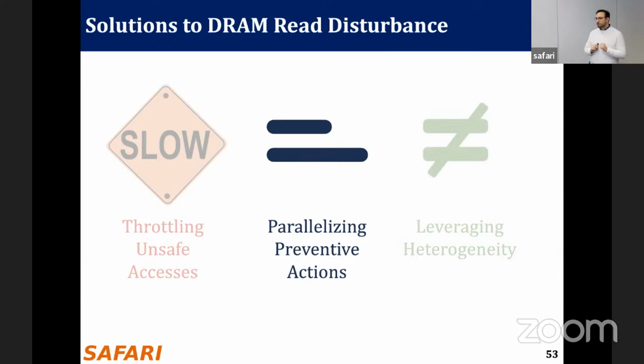But if you expose this information somehow, or you implement PARA inside the DRAM chip, so you don't have this restriction anymore, you can still have this kind of throttling support for those mechanisms. And that's a very good direction for follow-up papers. Nice.